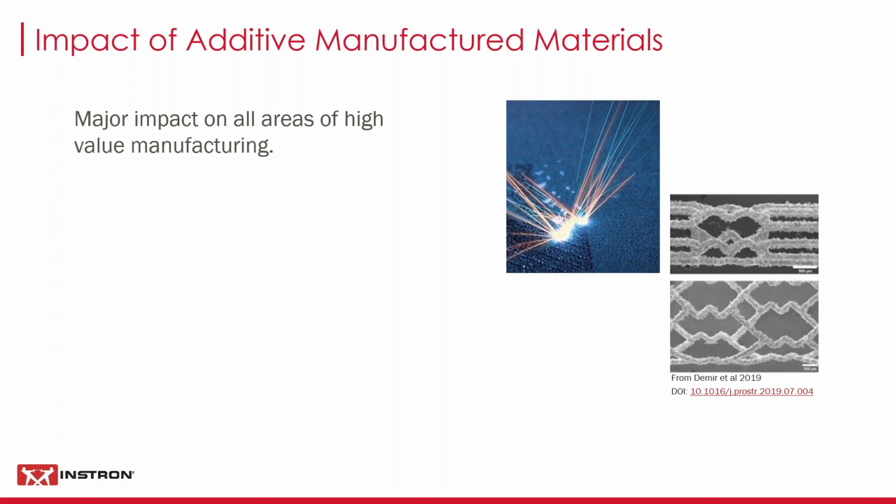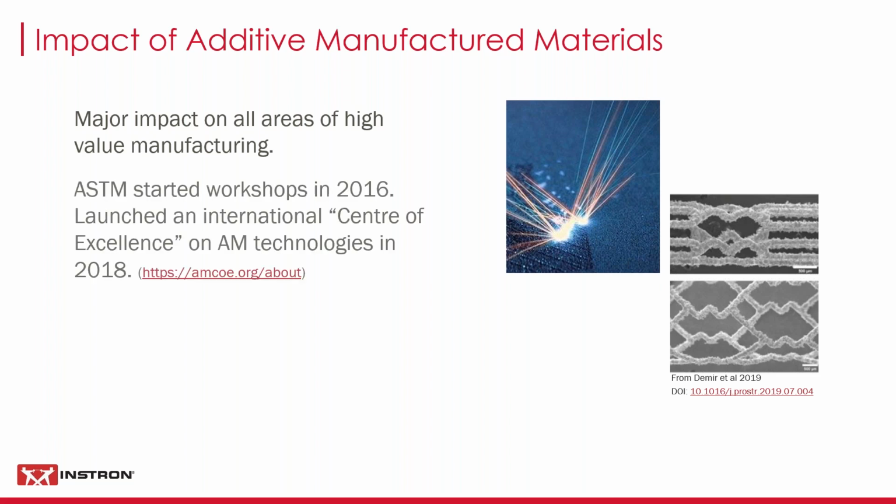This takes a lot of different forms, whether it's using UV curing polymers or melting and printing polymers, or in this case, more usually using an electron beam or a laser beam to melt metals together into the structure, into the pattern that you want.